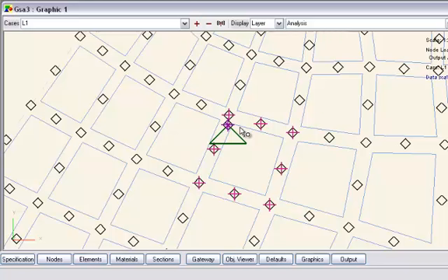What's happened is that there's now a tied interface, which means these elements here are all constrained. This node load will actually load up those elements equally, but the tied interface doesn't add stiffness. So rather than a rigid link, it's quite an intelligent way of dealing with these things.